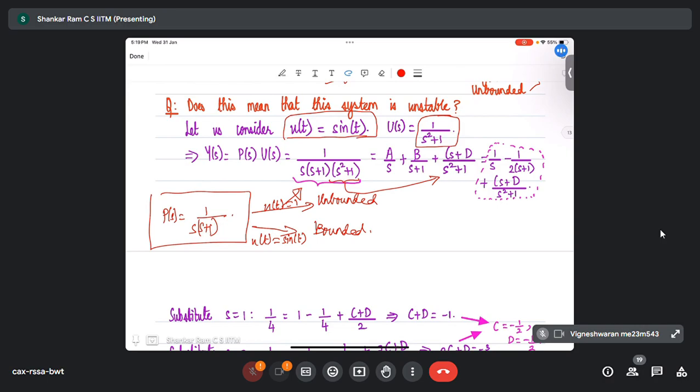If you look at it from a very pure perspective, as far as BIBO stability is concerned, what is the definition of BIBO stability? The output must be bounded for all possible bounded inputs, right? And for all time. Then the system is said to be BIBO stable. So I may have 100 bounded inputs in the world. I'm just taking 100 as a round number, right? Let's say for a system, I may have output to be bounded for 99 out of the 100 inputs. But if the output is unbounded for one bounded input, would I call the system unstable? By the definition, yes, unstable, right? But it is not so unstable as before, right?